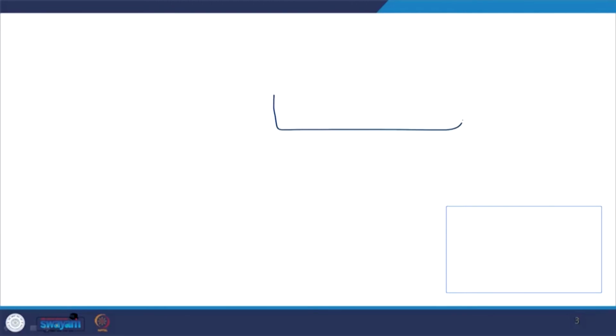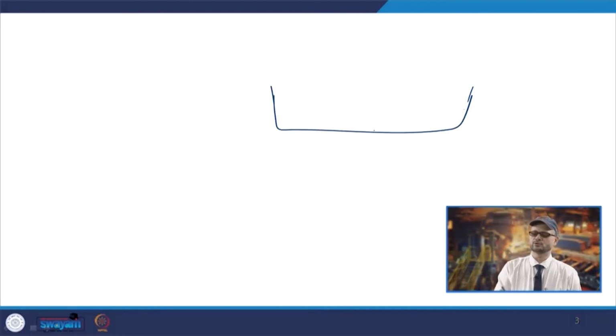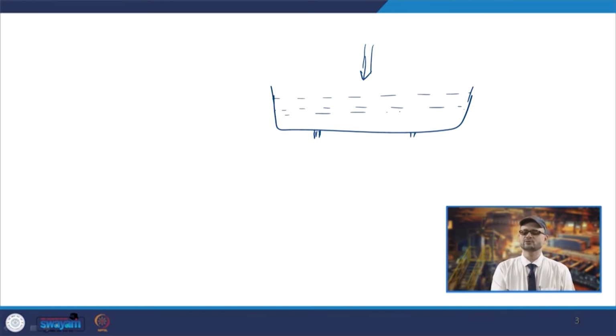So, what happens when the liquid level comes down can be understood like this. This is the Tundish, and suppose you have the outlet here. This is your inlet and the liquid metal will come out. You may use flame modifiers or so. Now, this is the level, and it will be coming down, and once it comes down to a certain level, you may have the formation of these vortexes, and this happens when the level falls to a certain